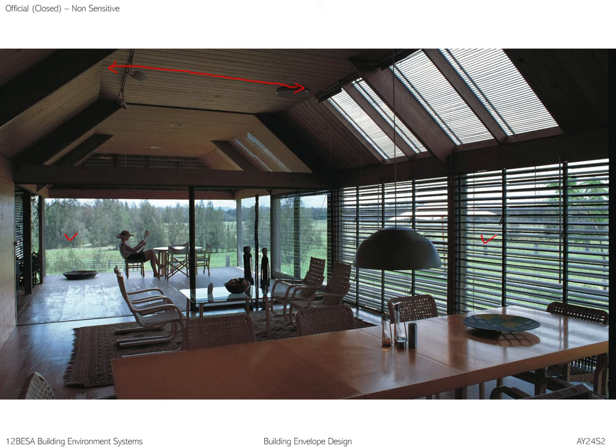Whereas for this phase, I want the view, I want the sunlight, but at the same time, I want to control it. These are roller blinds that you can pull all the way, and then there are louvers. They can use multiple layers of controlling devices. At some time it can be opaque, sometimes translucent, right? And sometimes if you want the fresh air, you might open up the glass and just use louvers. So the way they design walls is very interesting. It is a composite system.